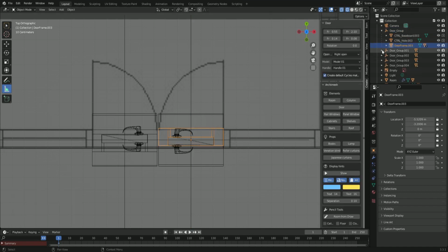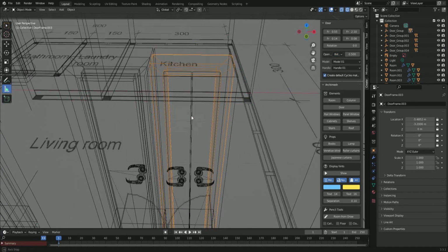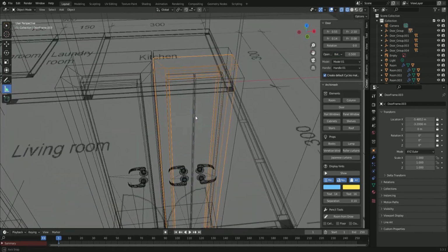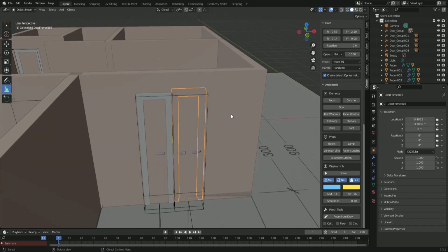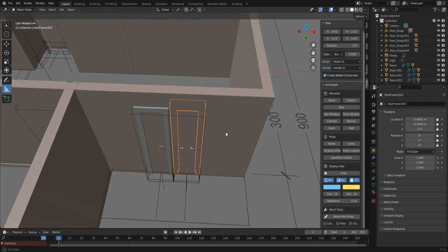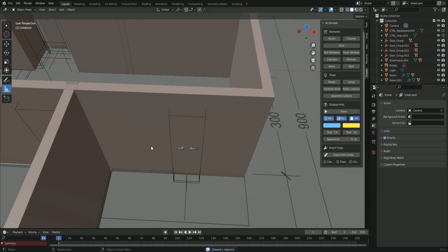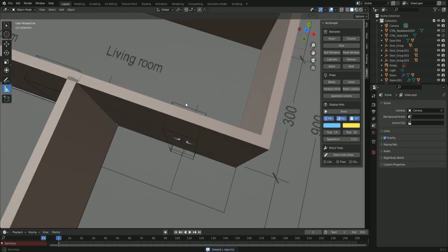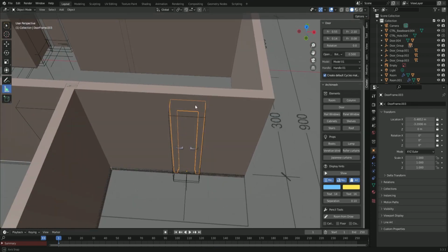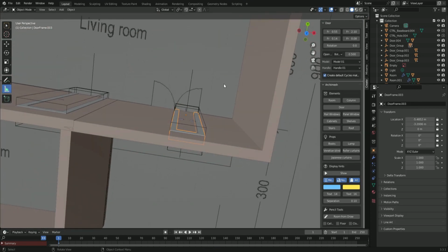Go to the top right, change to both sides. So you've got right side, left side, both, and look, you see the double handles. We can just get rid of the other single door. With both sides, you might get remnants of the old model left in place, just get rid of it. Increase the width, move it over, there you go, you've got your double doors.